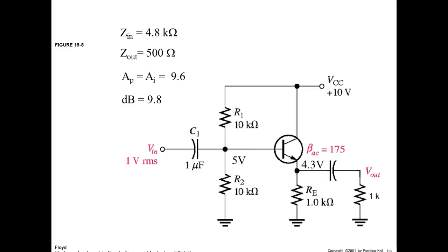So what do we use these guys for? Well, we use these guys to match a high impedance to a low impedance, right? These guys here will give you tons of current gain, but they don't give you any voltage gain. But that's no big deal. We can use common emitters. So this is why amplifiers go in what? They go in stages, right?